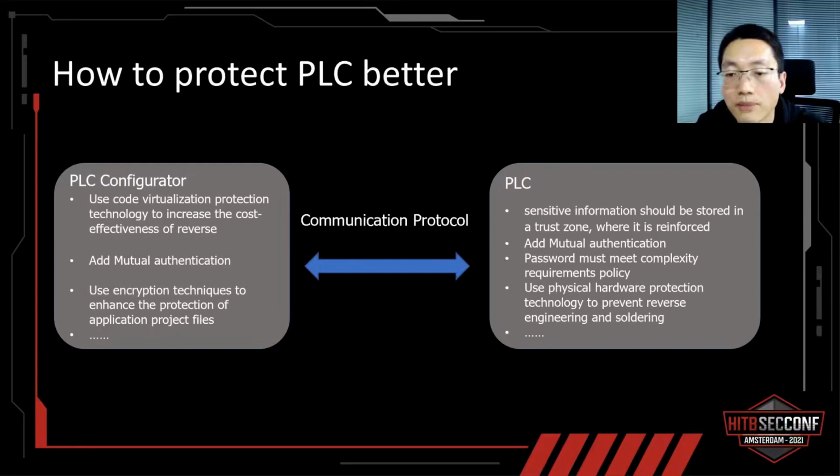The second is mutual authentication between the client and the PLC, so that the client and the PLC controller are authenticated mutually. The third is mandatory password strength settings. This is very necessary at this stage in the industry since few people set passwords for PLCs or only set weak passwords, which can be easily cracked by brute force attacks. A forced strong password can prevent such attacks.